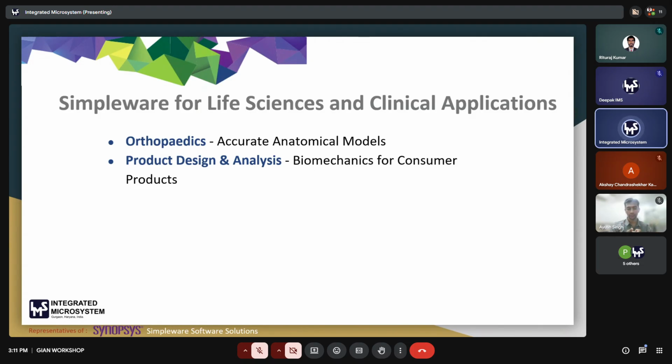What is the other way? The method is we have an existing design of any implant parts that can be modified and positioned in with the data set of the patient, and all the particular inputs that we are having. We can export it as STL files as a single printable object. So virtual surgical planning can also be conducted, and pre-surgical planning and post-surgical planning all get completed in the following section.